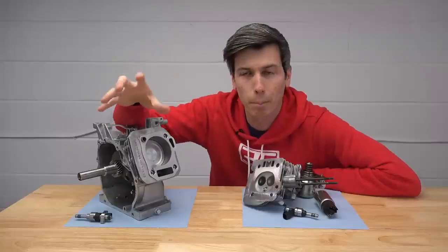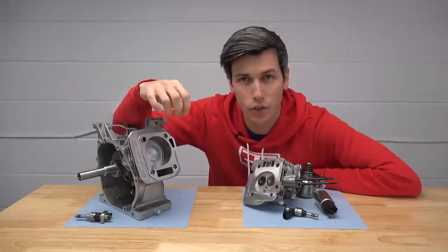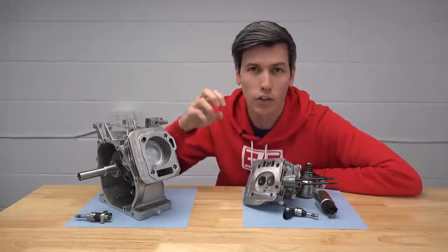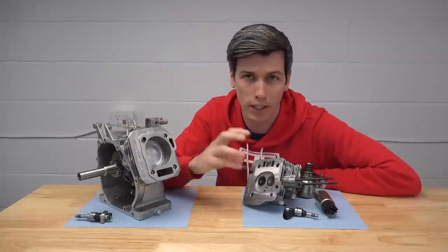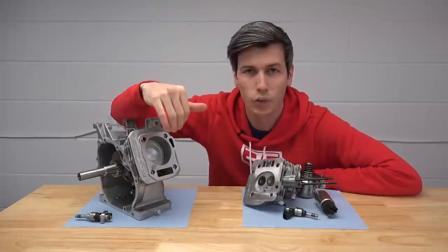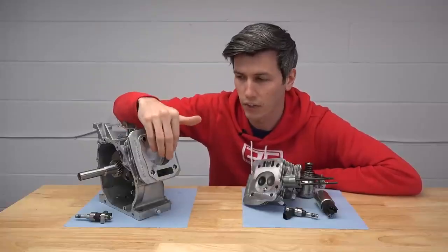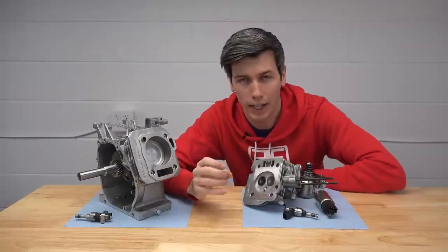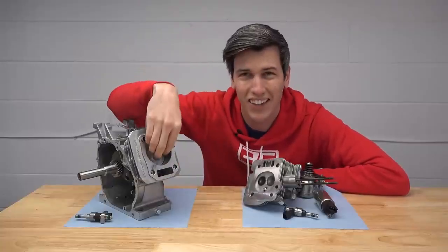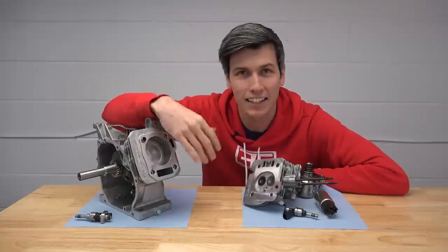Now, one of the major benefits of having that fuel injected directly into the cylinder is that it cools directly in the cylinder. So as that fuel changes from a liquid to a vapor, that vaporization causes a cooling effect. So you have lower temperatures within this cylinder. And that's really important for high-powered engines, because you're looking to make as much power as possible, you're packing a ton of heat in here, and that heat can lead to knock.